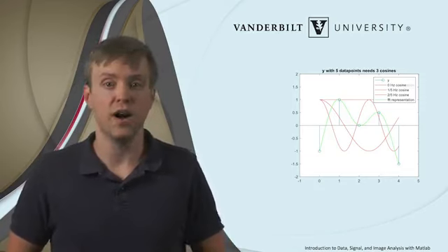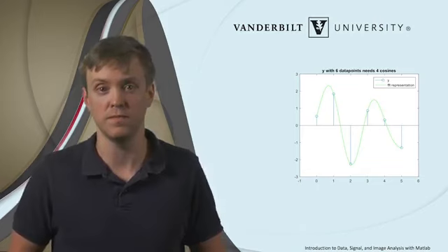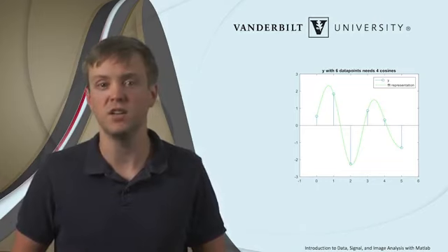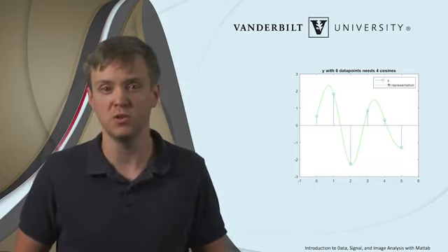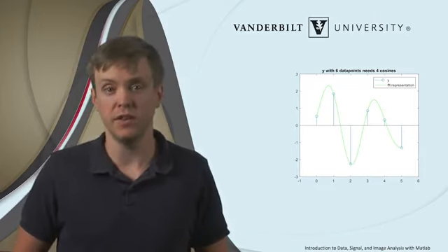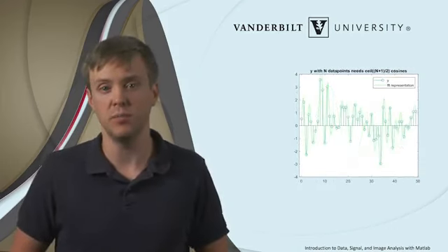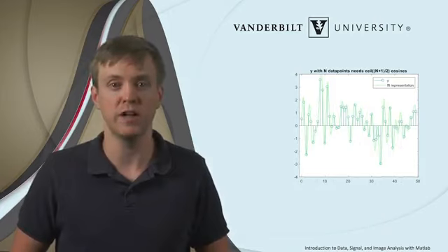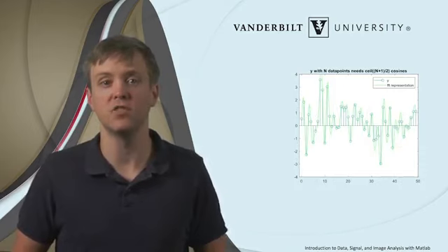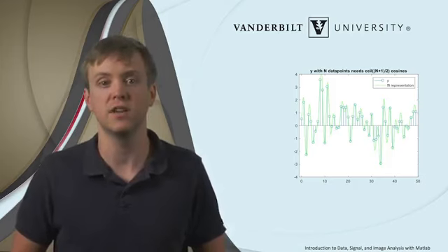Now here is a new signal y with 6 data points, but with values sampled from a normal random distribution. We need 4 cosines in this case, which becomes difficult to see if we continue to try to plot them here, so we just view the result. We could go arbitrarily high with this, but soon it gets too dense to plot. Here is a result with 50 data points in a normally distributed random valued signal y. As we can see, the FFT will always give us the right complex numbers to define the amplitudes and phases for a set of cosines to represent our signal.